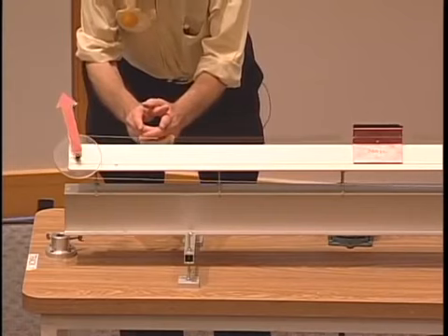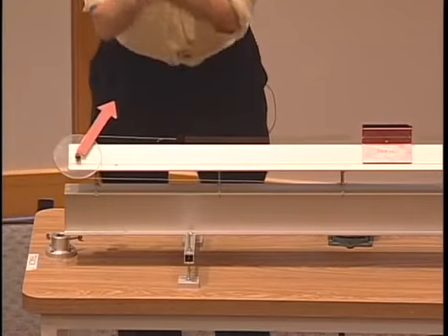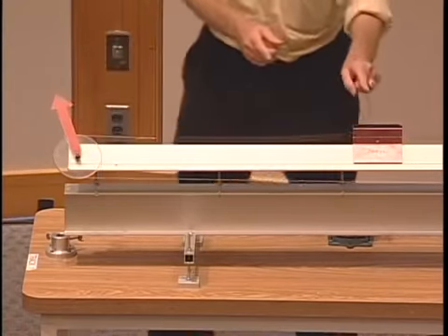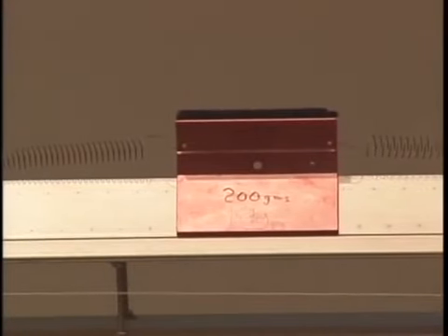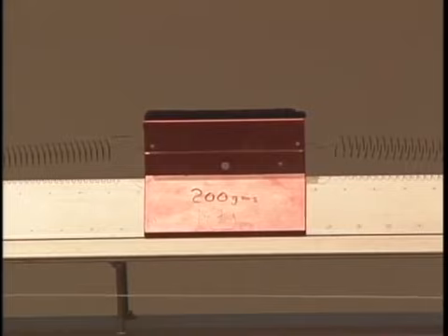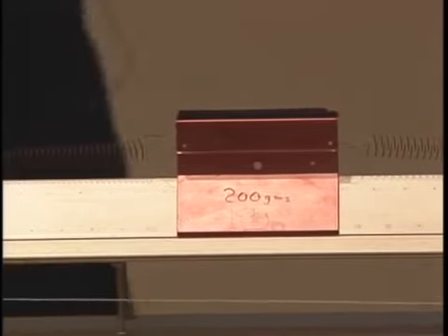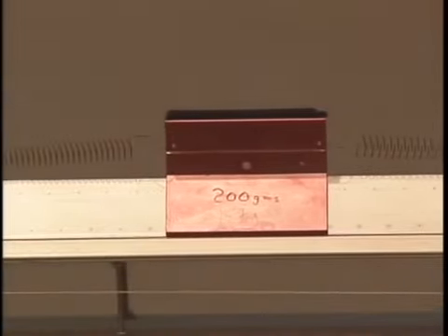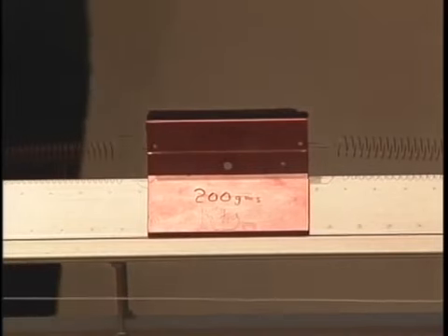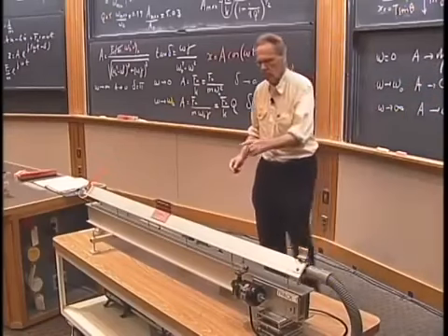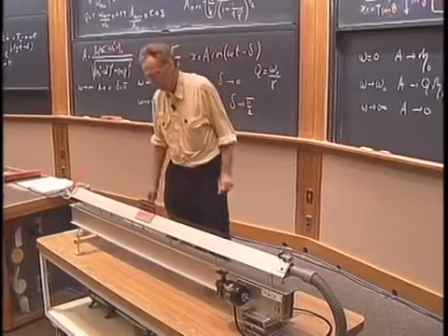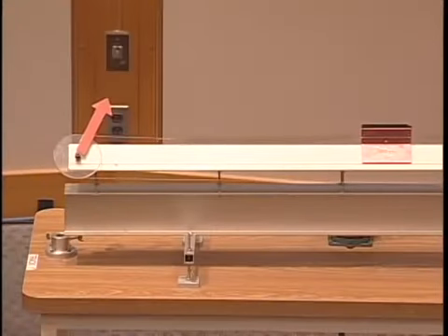Now, this was twice the amplitude of the driver, and when you look carefully here, it's less. It is that eta 0 over 2 that this gentleman immediately noticed, because we have two springs. So you see here, apart from the factor of 2, the delta 0, and you see that the amplitude, indeed, is half of the amplitude of the driver because of the two springs.